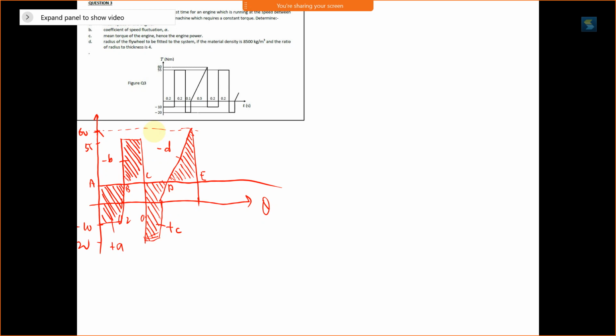Before we move to find the area, we have to make sure the parameters here are usable. Here it's 0.2, okay. This one should be 0.2 omega, here also 0.2 omega, here okay, but here we don't know the distance between here and here, isn't it? So we need to find it first, the distance there. So from here we have to use the interpolation method.